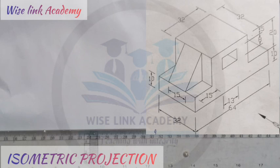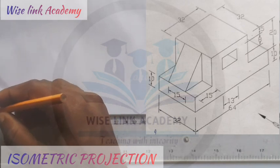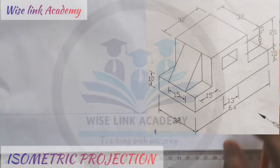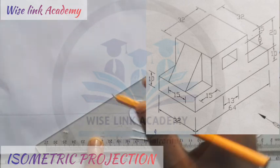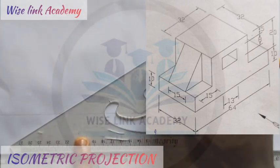So what is isometric axis? Here is what we mean by isometric axis. Your first task is that you take your T-square this way, draw a horizontal line this way, right? With the help of my T-square this way, incline at 30 degrees. I will take it this way, right?